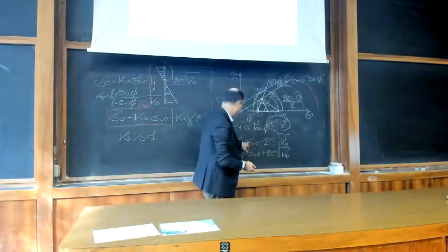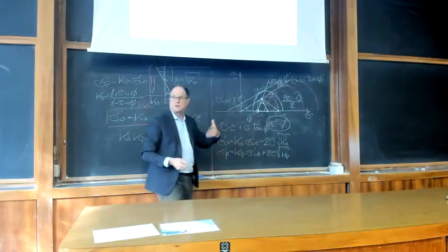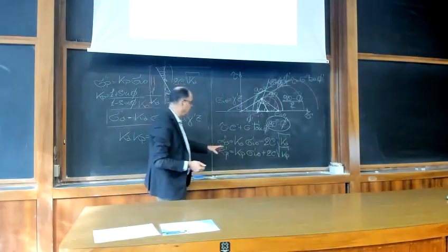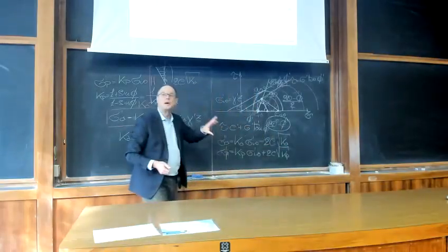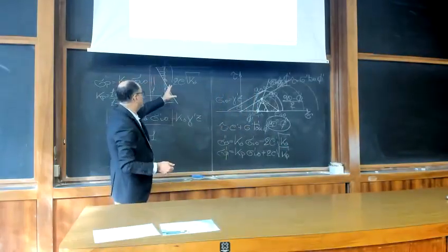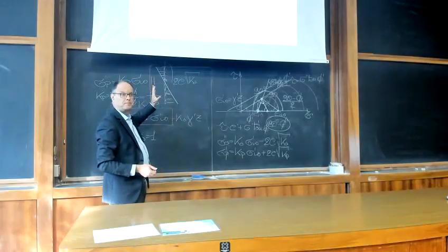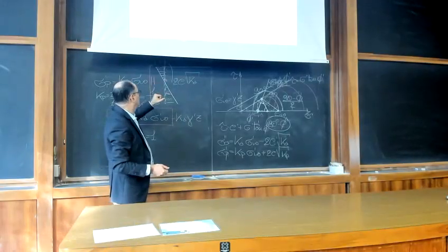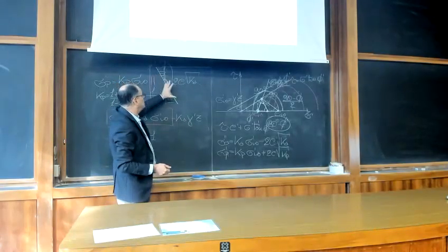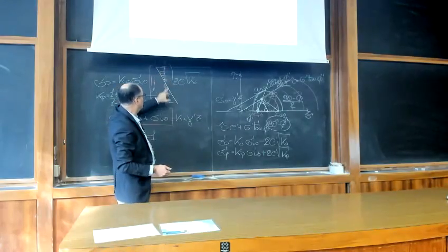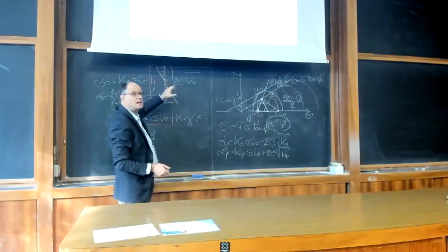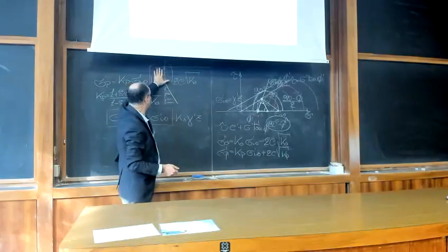Of course, this depends also on Ka, and Ka is a function of phi. But typically, the cohesion term will tend to reduce the active pressure. And it might be that your cohesion is very high, so that this is equivalent to this, and the resultant is zero, because this compensates this.